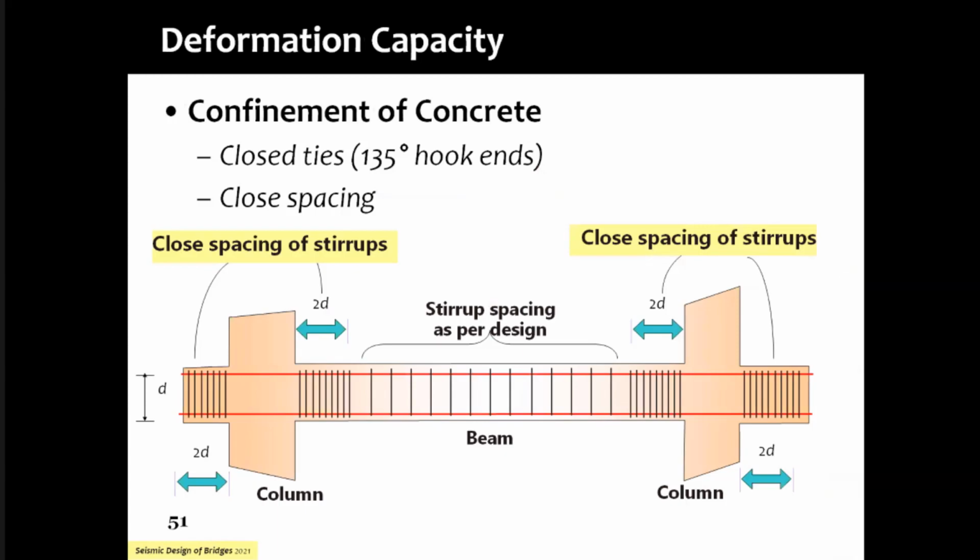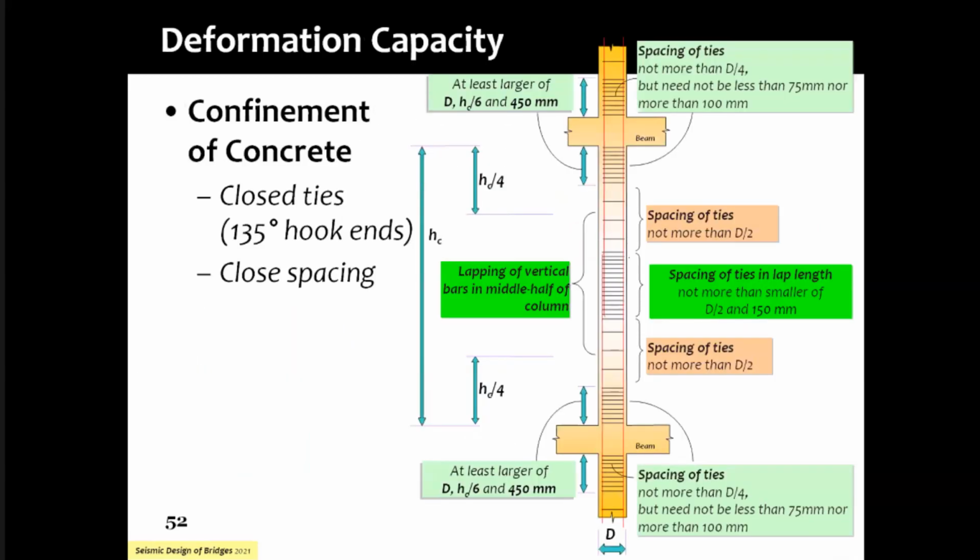Normally in buildings you want damage in the beams, and then in the columns, so you say I want hinges at the ends, so I'll do a close spacing at the ends so that I'll get good confinement there. Very good. Sometimes, even building columns will swing back and forth because I have done a bad design, and the hinges will form in the columns because I made them skinny. I took 230 mm columns, so columns also will form hinges.